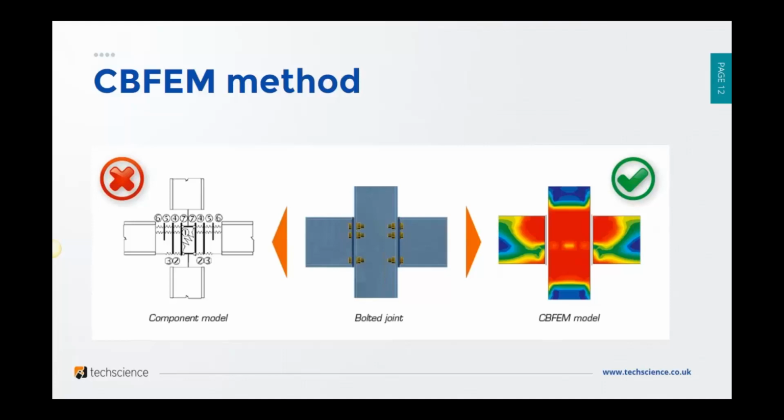Force interpolation constraints are used for the welds. Nonlinear springs are used for bolts and anchors. And contact elements between plates in the connection. So we have special contact elements that are positioned between a base plate, for example, and the concrete block.